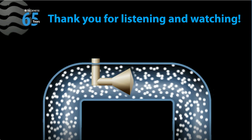Yeah, and I've seen some at the factory that have several different ports on them for transmitters, and so they can pretty much let us know what they need as far as the inputs and outputs, correct? Absolutely. Whether it's multiple sets of taps or different types of taps, it's a customizable product, so it's really engineered to whatever the operator's needs are. We've done pipe taps, flange taps, MPT couplings, direct mount plates. I mean, you name it, as long as it can be welded on top of the pipe, it's a tap type that we can offer. And of course, extra sets of taps for safety instrumented systems is a specialty of ours too.